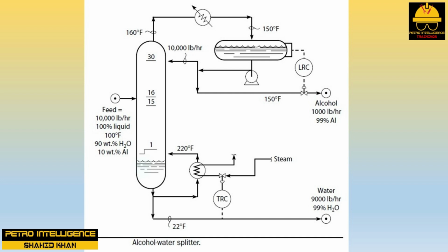Now let's look at the reflux drum. The incremental reflux flow comes from this drum. But the liquid in this drum comes from the condenser. The feed to the condenser is vapor from the top of the tower. Hence, as we increase the reflux flow, the vapor rate from the top of the tower must increase. One way of summarizing these results is to say that the reflux comes from the reboiler.